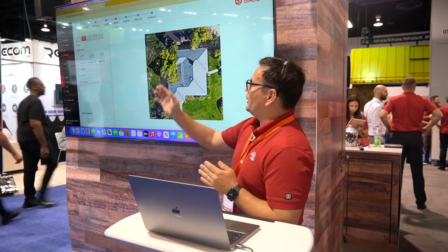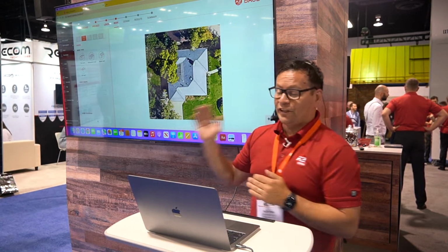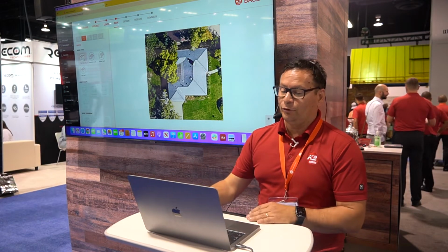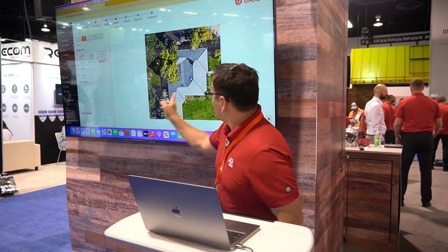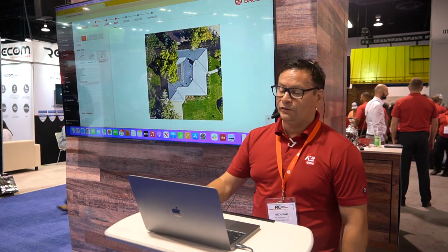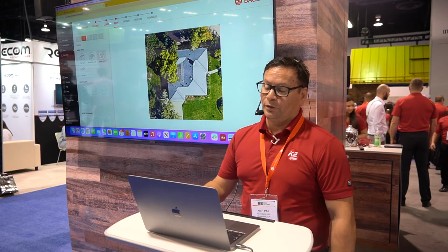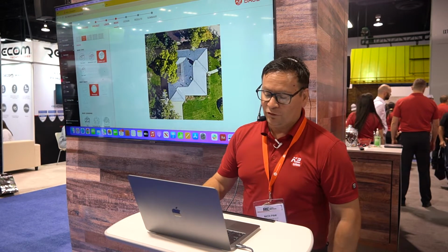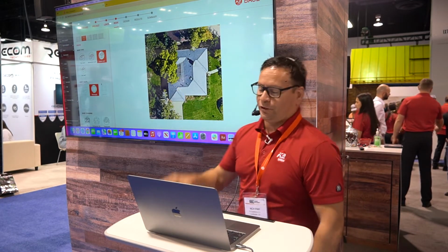From there, you'll see that it is itemized over to roof, and we're going to take a look at the building here, and this is where we actually get to draw our array on the actual roof here. It's going to ask us a couple questions about the actual structure. Is it a flat roof? Is it a mono-pitch roof? Is it a gabled roof? Is it a hipped roof? We're going to be installing particularly right here on the actual front of the house, so I'm just going to go ahead and click gable so we don't have to draw a trapezoid across it. So we're just going to put a rectangle of solar right across here.